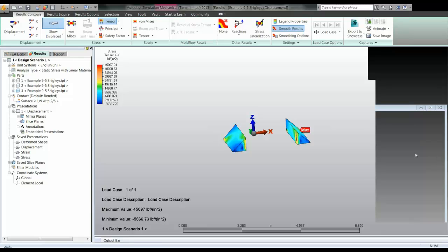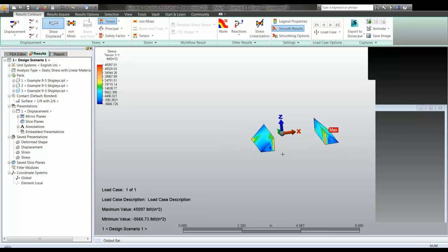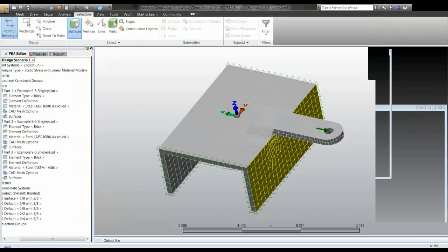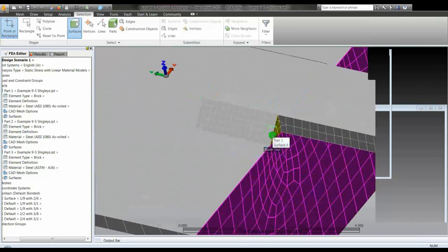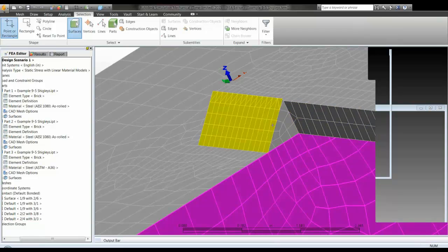I see the questions in the chat. James, you'll want to look at the questions panel. Here's a question for you, James. Unrelated question, how can you create a new coordinate frame if one that loads from the CAD is not oriented correctly? Local coordinate system. Let's do that. We'll do a rectangular coordinate system that will follow the throat of the weld.